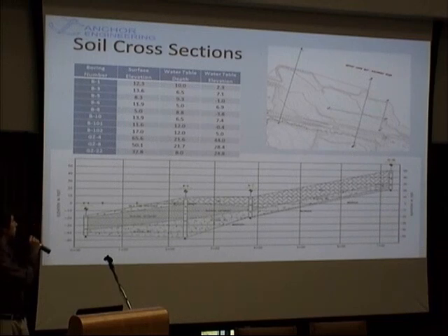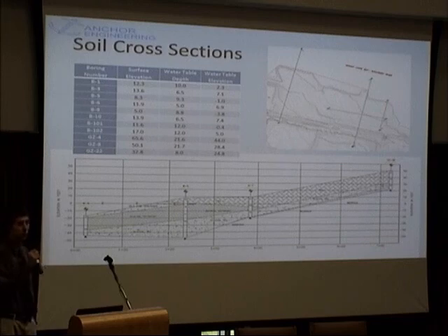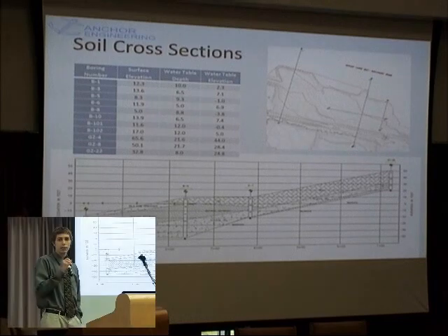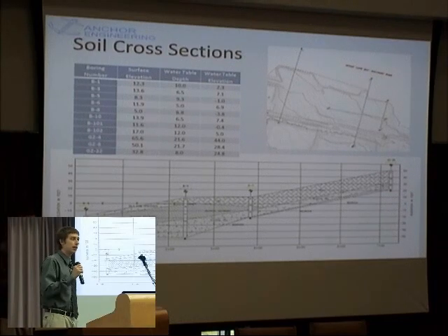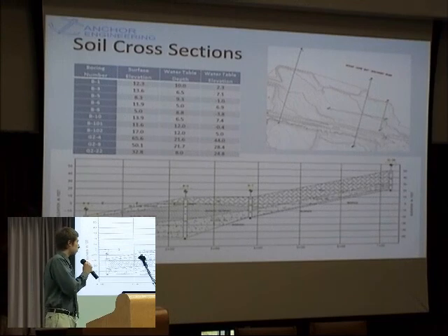And from these cross-sections, we can see that the surface soil on the site is fairly dense but uncontrolled fill. It's filled with a lot of debris, boulders, pieces of wood, trace organics, so I did not consider it structurally sound. Fortunately, since we need to raise the grade of the entire site above flood levels, that gives us plenty of room to fill in the site with structural fill.